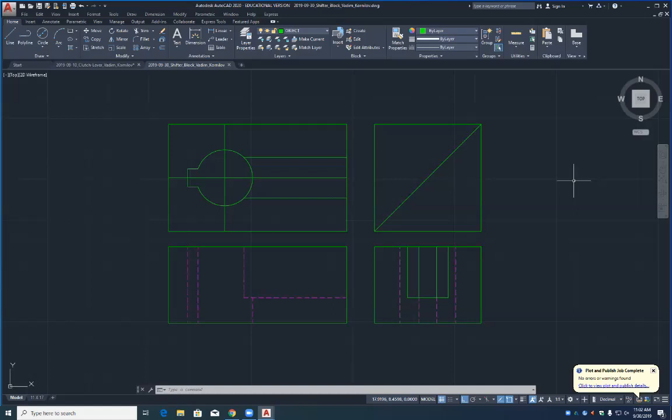So critical concept now. According to our drawing, in our right side view, this hole is offset 1.31 coming over here, correct? And it's up 1.25 right here. Okay? So let's do that. Let's offset 1.31. I'm going to come over from here and offset 1.12 coming up. There's my center point for my hole, right?